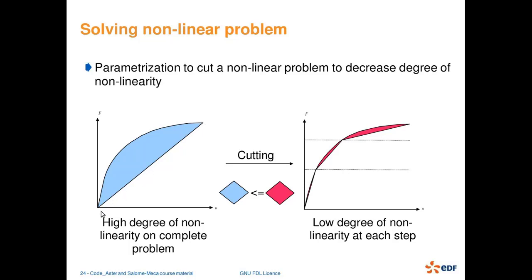Therefore, since any curve can be taken as made up of small segments of straight lines, we can cut it down into various steps. Say this nonlinear load is provided in a number of steps, thereby reducing the nonlinearity in every step. So that is another reason why we need to take the load or deformation as a function of time.